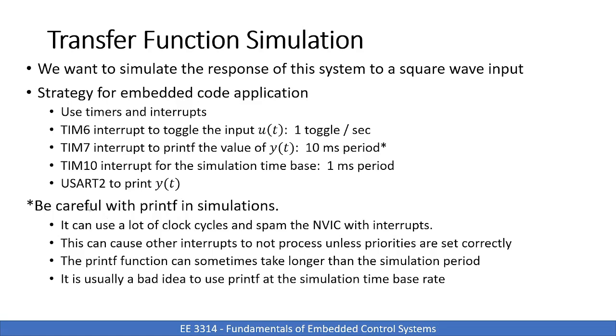And down here I basically just remind you to be careful with printf. If you printf everything as fast as it's happening, you run the risk of really bogging down the simulation and having some of these interrupts stepping over each other and maybe not finishing a calculation before the next interrupt is triggered. That's kind of outside the scope of this class, but just know that if you have a lot of things happening in a callback function, you want to make sure that the period of that callback function is long enough to do all those calculations, or else they'll start running into each other.